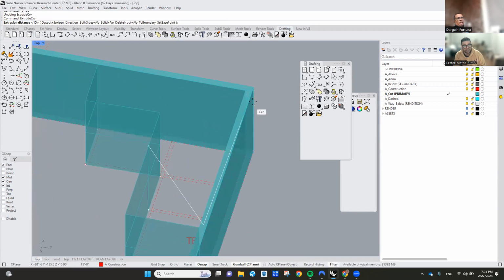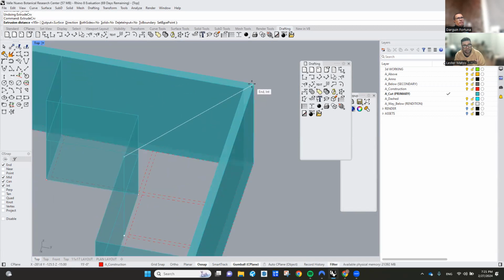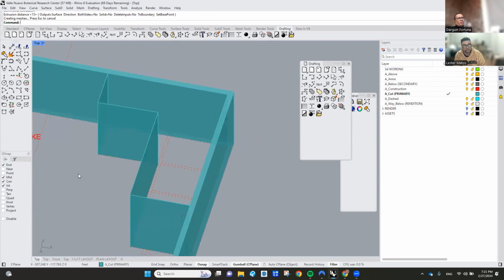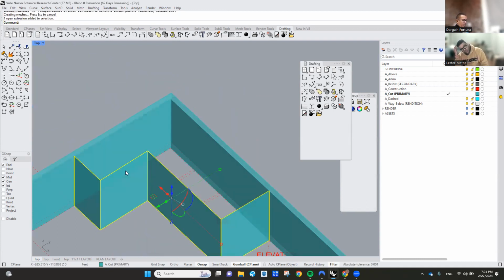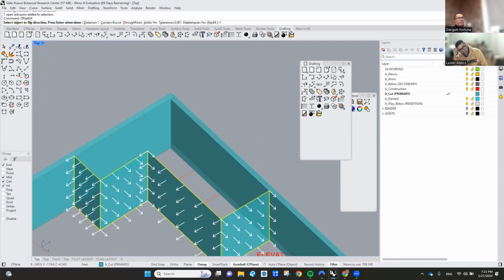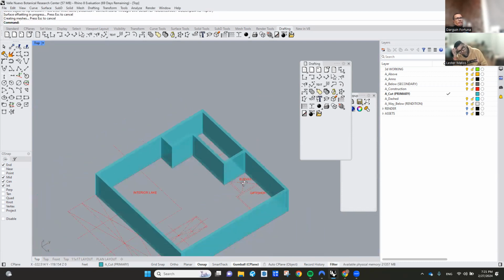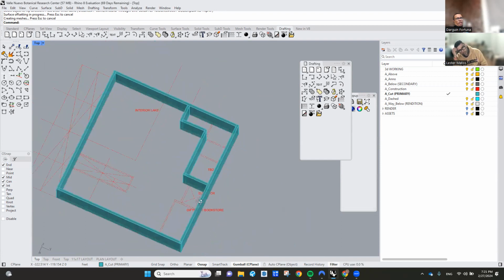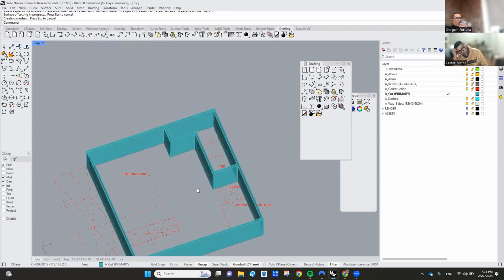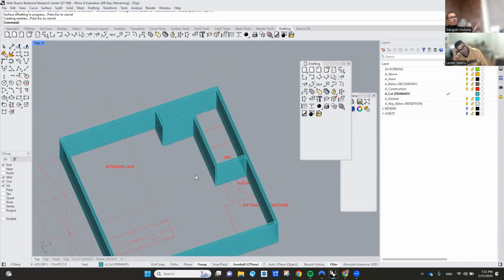I would pick an element that you feel good with. And then you can grab this, offset, surface, what direction, flip the other side, enter. You have your walls. That's easier if you have them all joined. That's very easy. Now that said, I already showed you how to do that. You can do that on your own. You don't need me for that.